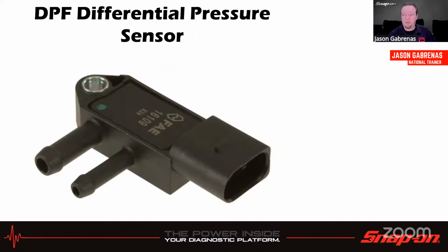DPF differential pressure sensor is going to measure the inlet versus the outlet, and it's going to tell the PCM how clogged the DPF is. Another reading you'll see is DPF outlet pressure, which is basically back pressure coming out of the muffler. So we're going to have two hoses. One goes into the inlet, one goes to the outlet, and it's going to measure the difference in pressure between the front and the back and see whether or not it's clogged.